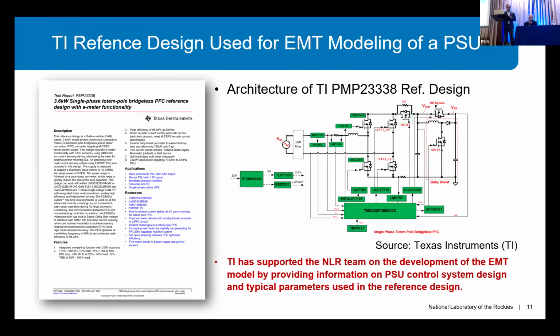Now there's a question. Just like IBRs, do we want to go towards black box vendor specific models of IT racks and PSUs, or do we just use this generic model? I think because the IT racks are way down the electrical distribution network, and because they're highly standardized products, generic models would be good enough, but that is just my opinion.